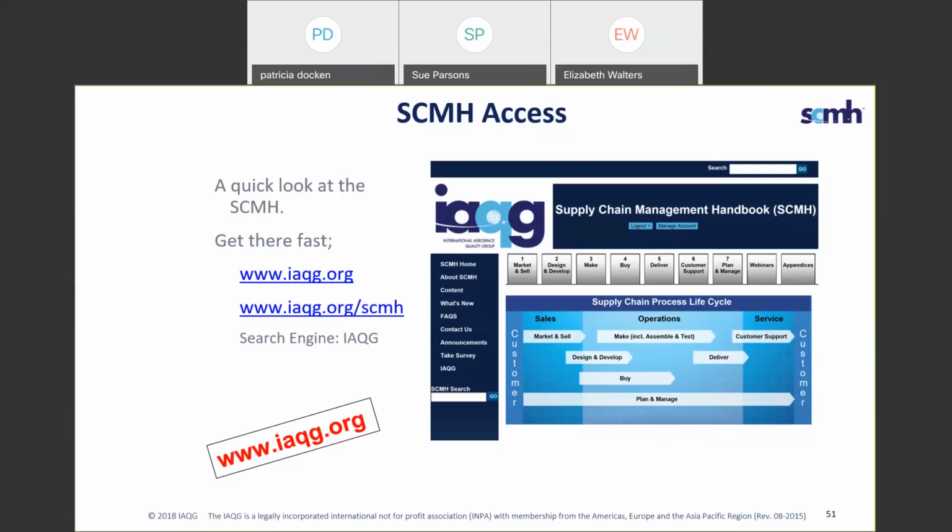Attribute characteristics are also KC. Please confirm. Yes, it could be. A key characteristic could be a pass, fail, go, no-go type of a characteristic, sure. And you still would want to manage the variation on that if it's a key characteristic.